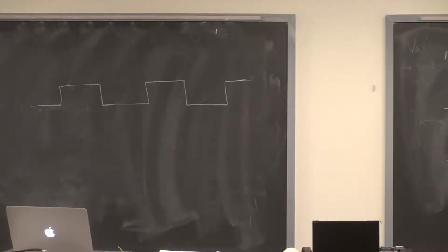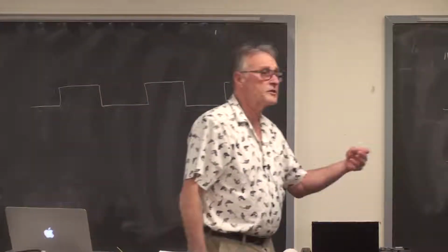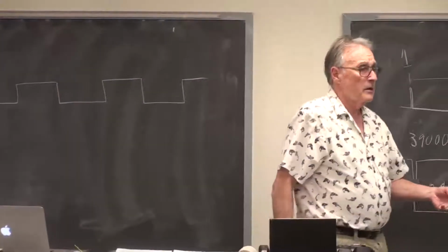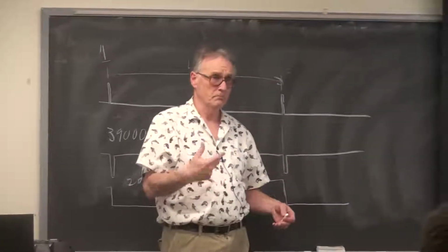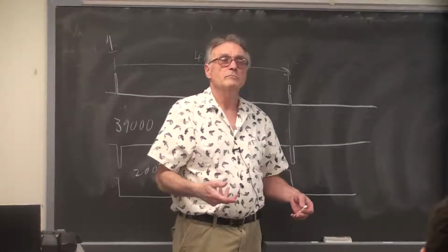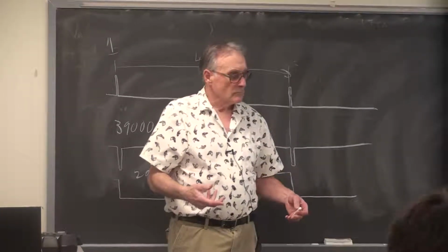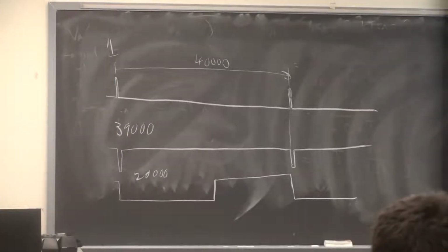In this case, this statement, this PWM on time set, is going to be in the interrupt service routine. So once a millisecond, you're going to change the PWM on time according to your control algorithm. Any questions on that?